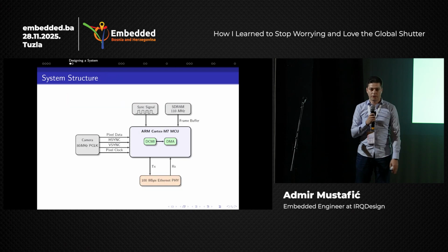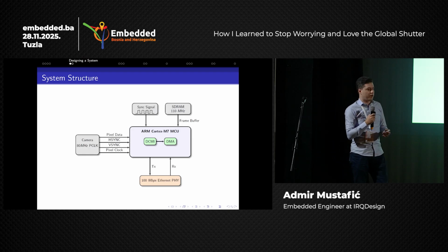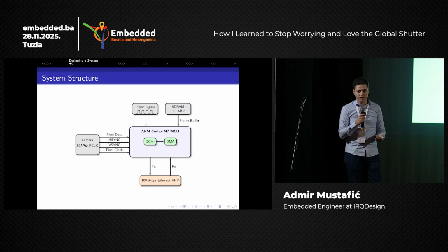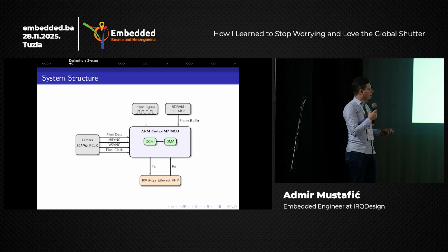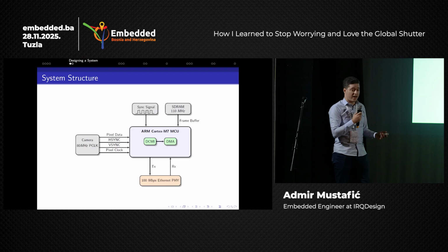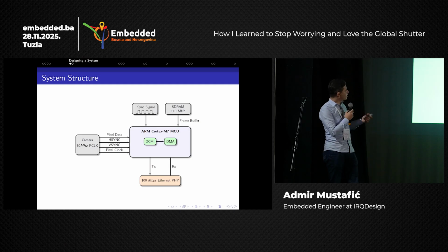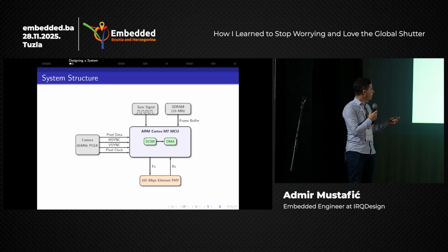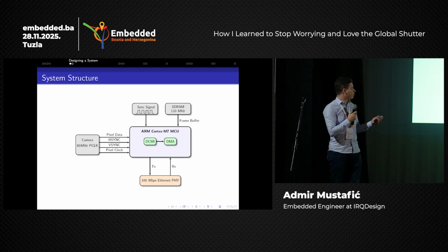How do you approach designing a system that will be capable of capturing such images or mimicking a global shutter whilst having reasonable cost components? As mentioned, many cameras in the lower cost range do not have the global shutter effect since their architecture is much more complex than the classical rolling shutter. An example of one such system is to have an ARM-based Cortex-M7 microcontroller chip with the capabilities of the digital camera parallel interface coupled with the DMA.